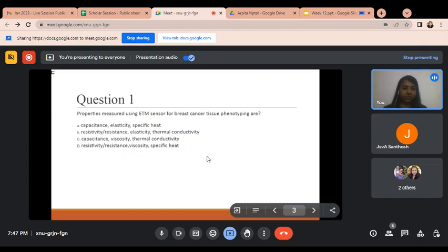All of you have gone through the video lecture of Dr. Hardik J. Pandya, so I think you will be able to answer this question. Take your time, there is no hurry. You have seen this type of diaphragm, and there is some piezoelectric material present, and from the back side we etch, and this type of shape is there. So if some pressure or force is applied, then if it is piezo-resistive, the resistance of this material will change, and if it is piezoelectric, then the voltage will change. So how to fabricate this type of device? Take your time and then try to give the answer.